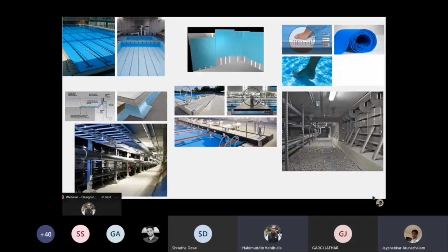So when someone was asking about the waterproofing and the leakages on the joints, between the two panels we have a special PVC T-joint, which is inserted and is then sealed. There's a double sealing with liquid PVC that happens. So that's between the panels. And then between the panel and the floor, we have the hot fusing, the fusing with hot air of the special PVC membrane with the PVC on the stainless steel panel, which is factory laminated.